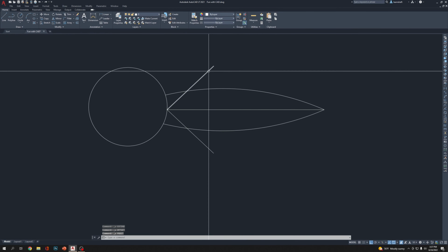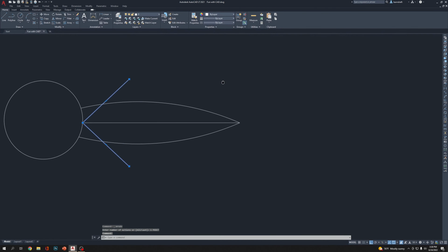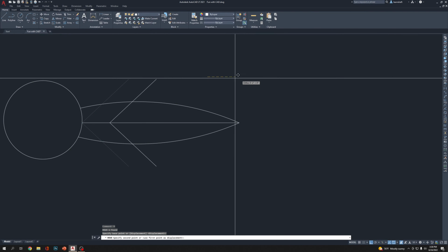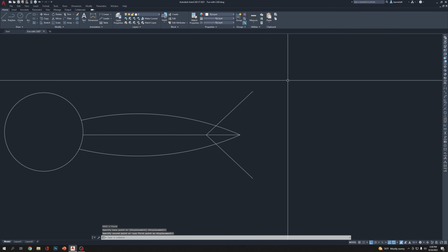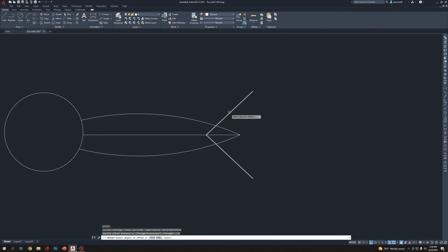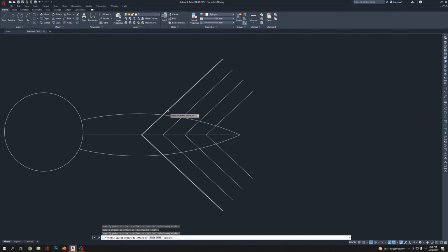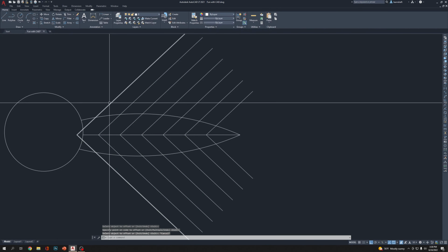Okay, it's one line. Now I'm gonna click on this one or press Control U to undo. So I'm gonna click here because this line has already become one line. I'm moving it until here. Okay, now we are going to offset it. O, enter, 0.75, enter. Now it's become bigger, not smaller. Make sense? This is called fun with AutoCAD.